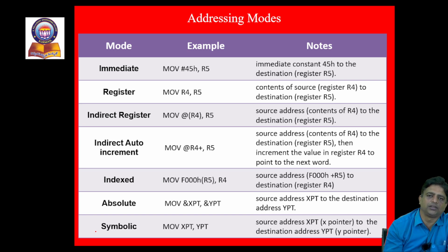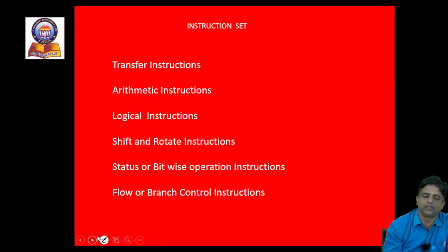Very basic and user-friendly addressing modes. In connection to memory operation, we can use indirect addressing mode or direct addressing mode, and sometimes indexed addressing modes. In continuation, as we obtain some operand, the various operations that we can perform on that operand can be decided with some set of opcodes.